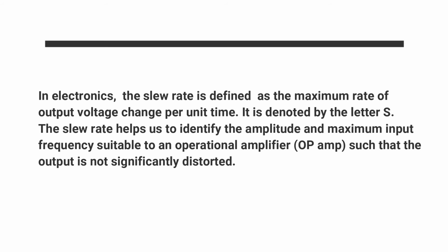As for question 2b, what is slew rate? Slew rate is defined as the maximum rate of output voltage change per unit time. It is denoted by the letter S. If asked whether it is important, yes it is. The slew rate helps us to identify the amplitude and maximum input frequency suitable for an operational amplifier, such that the output is not significantly distorted.